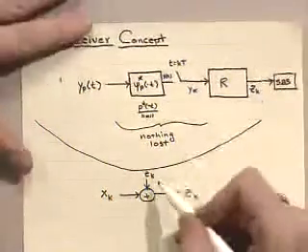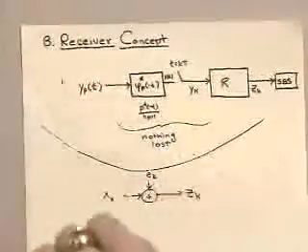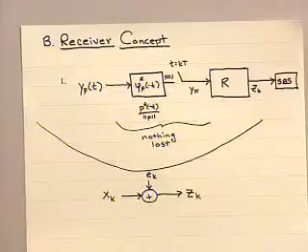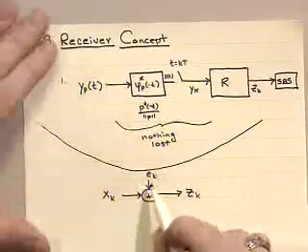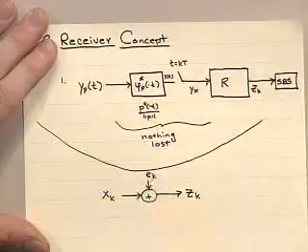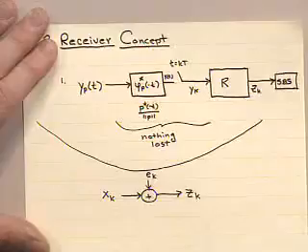In fact, even if the error signal is not white, I'm going to treat it like it's white because I'm doing symbol-by-symbol detection at that point. And what I really care about is the variance of the noise at time k, the variance of the error, I should say, at time k, and the signal power that made it through to Z sub k.